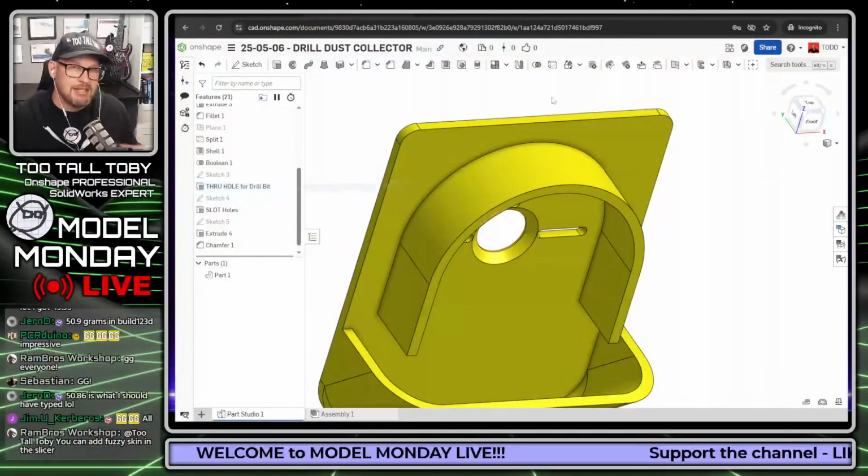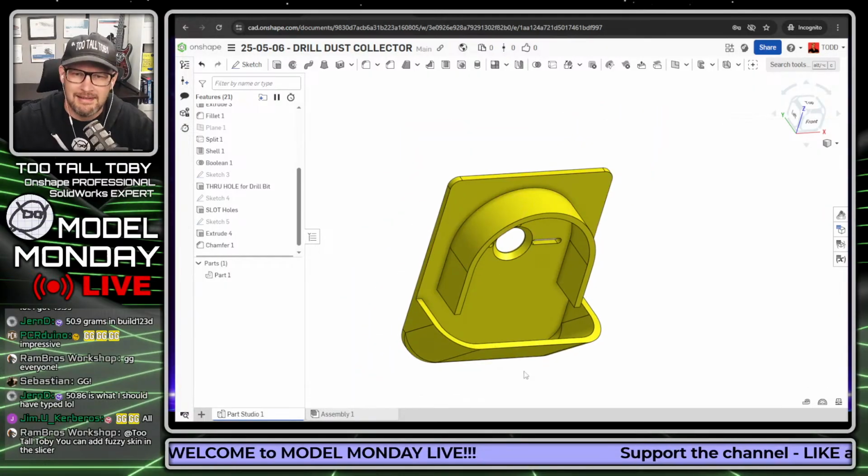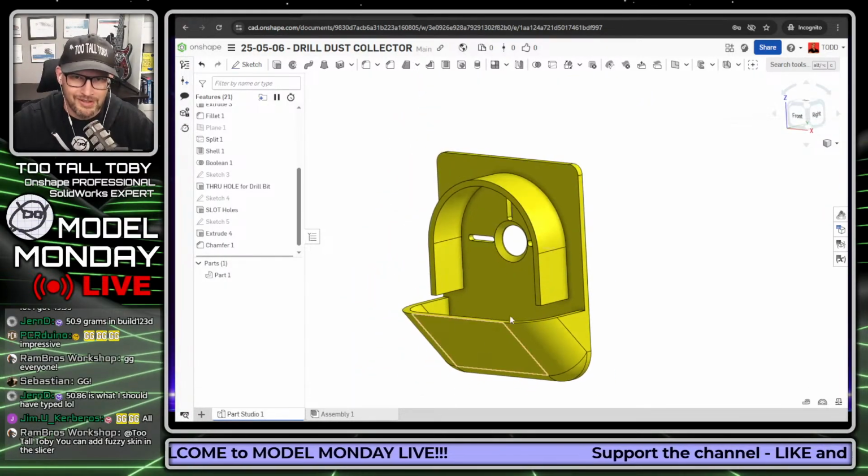Rambros Workshop says you could add fuzzy skin to the slicer. Yeah, that's a good point too. We could texture this thing a little bit in the slicer as well, and that might take care of it. But just thinking geometrically, that might be something I consider. The chamfer and the wall thickness are the big two, though. That thumb thing, I have to actually use it myself to really decide if it's that important.